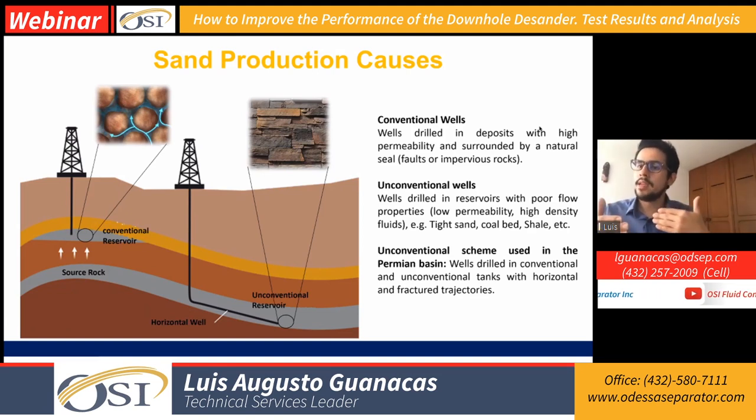It is so critical, and I want to highlight this fact because sometimes we have initial wells that start production, and then we see how these wells need different interventions because of downhole problems, because perforations plug, or because maybe they are using a gravel pack or a different type of completion, and this is affecting the performance of the well. So it is so important to address this problem before we drill the well. Okay, let's move to the next one.